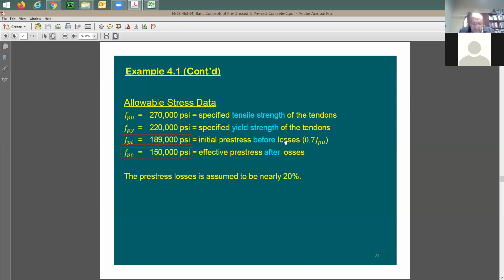We don't have time for that. We need to move faster because the construction bed in the factory is expensive. So you'd like to put a beam, cast the concrete, put the PT after, let's say, a week or less, and then just take it out, move it, and then put the next. So we need the equipment, we need the form, we need the place. We don't have time to wait for 28 days, and then after that apply the pre-stress.